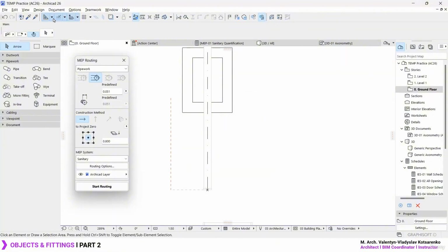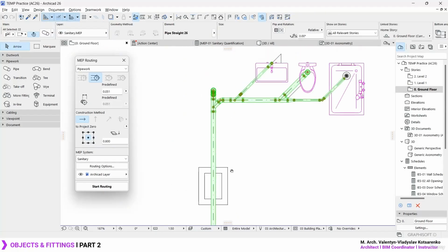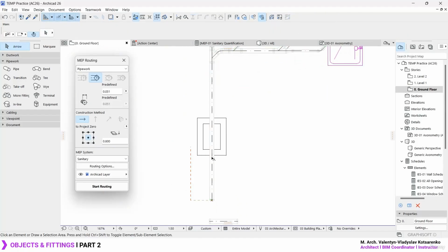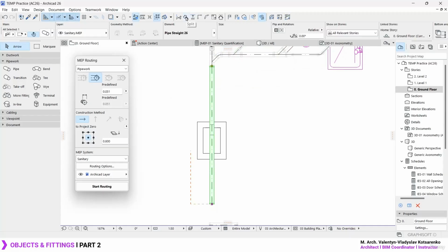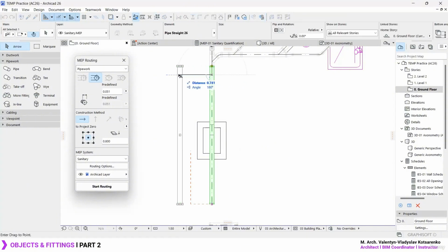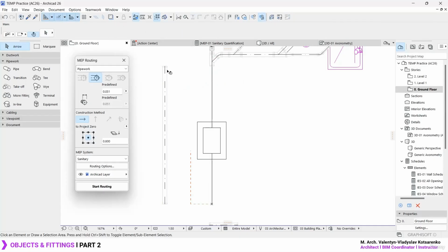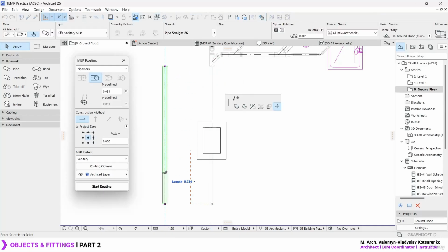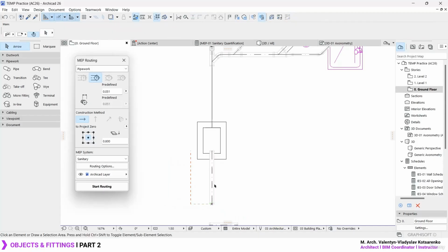Okay, don't forget that if you want to draw manual guidelines, you simply press Alt plus L or simply activate it over here. Okay, let's see if we can actually divide this pipe into 2 segments with the split tool. Let's see if it's going to allow us. Nope, it's not going. So for this case, I'm just going to move this pipe so it disconnects everything from the system, make it smaller, and adjust it until this point. Okay, now going to move the pipe in line once again.